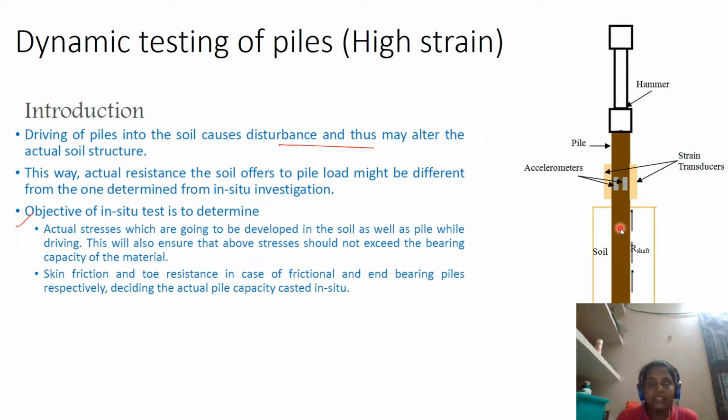While it is penetrating, we have to check whether the stresses being developed in the pile are what we have calculated. So two things are there. The stresses caused while the hammer is dropping should not cause any destruction to the pile, and also when it is being inserted, it should not cause a reduction in the bearing capacity of the soil because of the disturbance or the stresses created by the impact load. So this high strain dynamic test is mainly to find out the stresses that are created. That is the first thing.